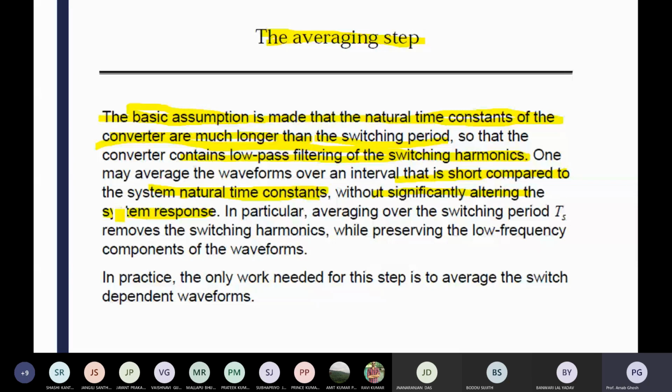Practically, rise time and overshoot are inversely proportional. If rise time is less, overshoot will be high, meaning the response is very fast. If overshoot is less, rise time will be more. So you have to design it such that the rise time is moderately less and the overshoot is moderately less. Both should be like that, so you have to select in that manner.